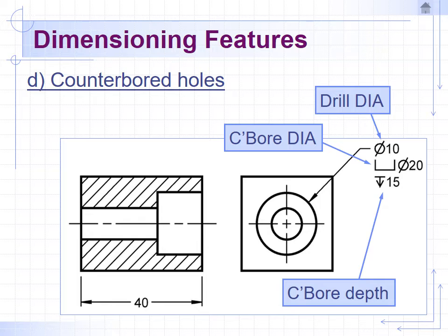Then they come back with a different drill, or sometimes it's a two-part drill now that everything's so fancy, but in the olden days, there would have been a separate tool that would have been applied to this that would have had a stop on it so it didn't overbore this part, this depth, and then created a little wider pocket. And then that part of the work is where the nut goes. And so it has to be sized, you know, if your nut head is in here, it has to be sized so that you could get a socket wrench inside that counterbore.